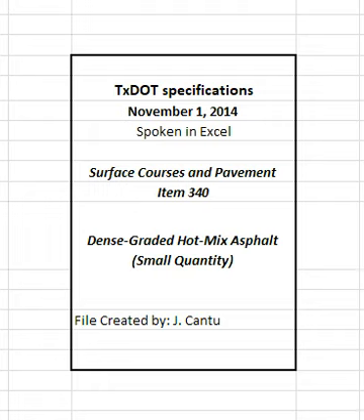Meet the master gradation limits shown in Table 8, and be within the operational tolerances of the current JMF listed in Table 11. The engineer may adjust the asphalt binder content to maintain desirable laboratory density near the optimum value while achieving other mix requirements. Table 11. Operational tolerances. See table in specifications.